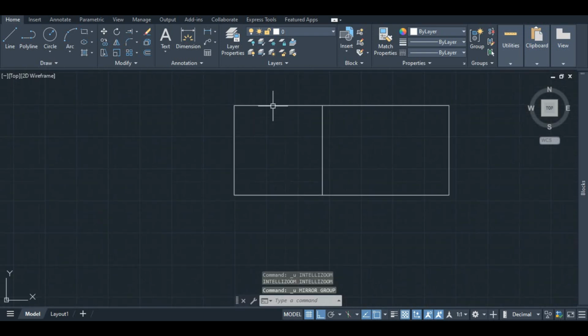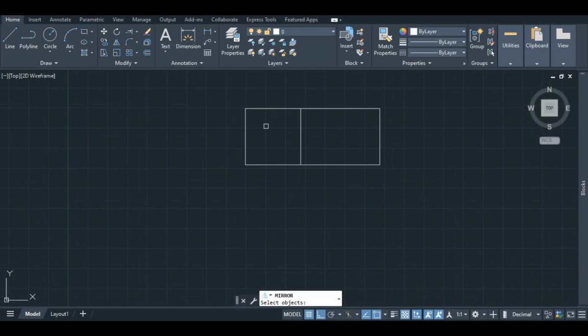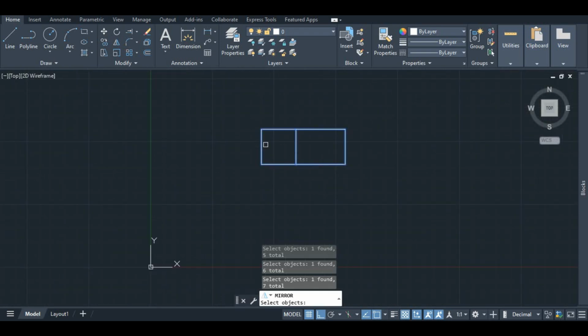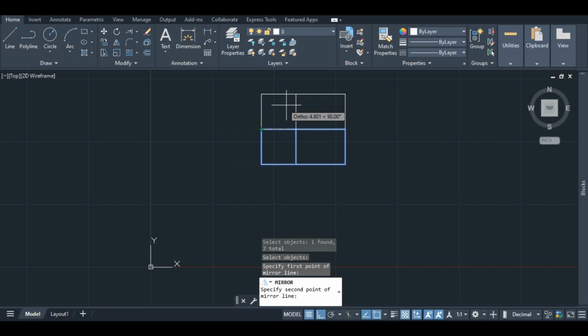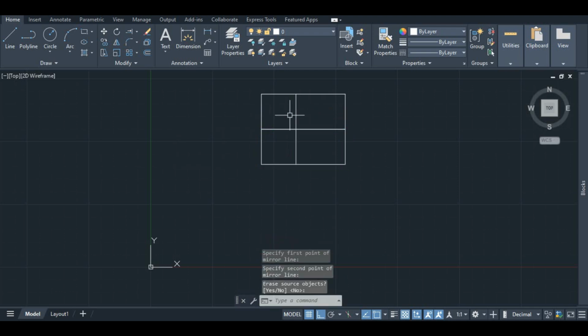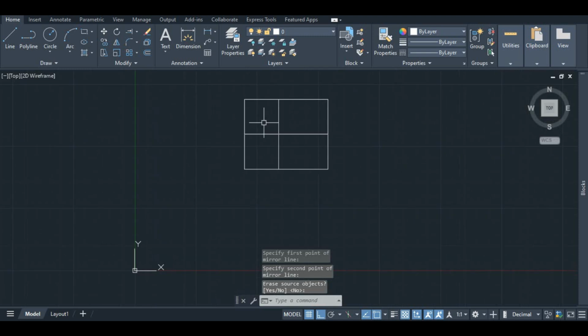but I prefer to just let us have it straight up like that, and let's try to mirror the object in a way that creates an inverse of what we have. So enter, then you pick a reference point. So I'm picking this reference point again, and I'm mirroring it here, you understand, and then I press enter. So that's what the mirror tool does.